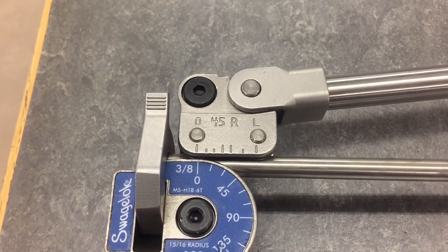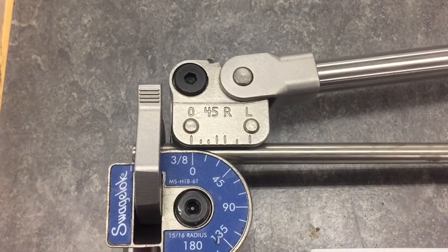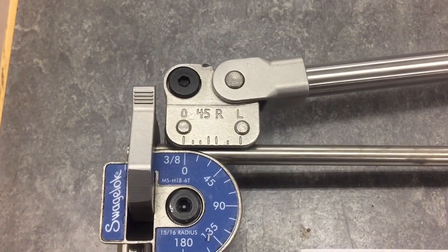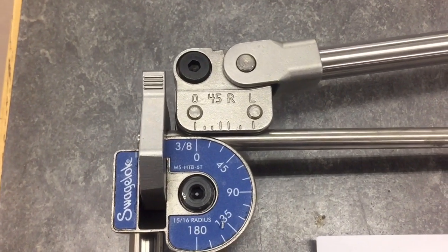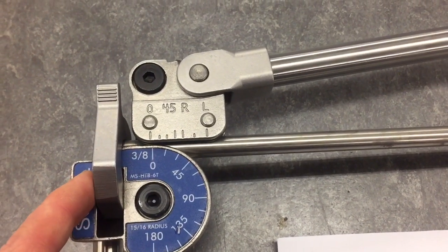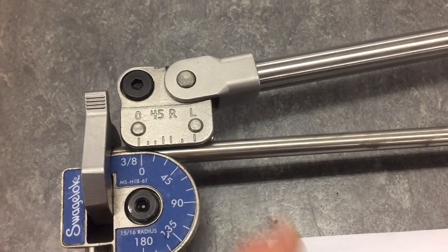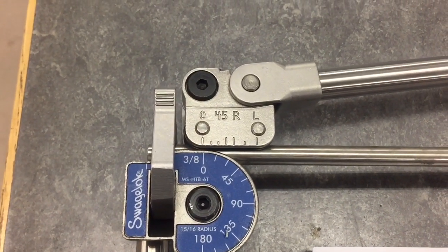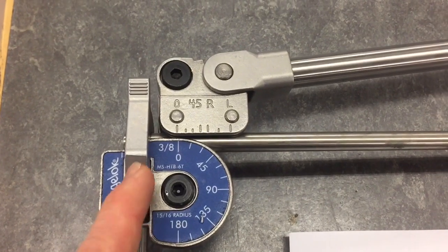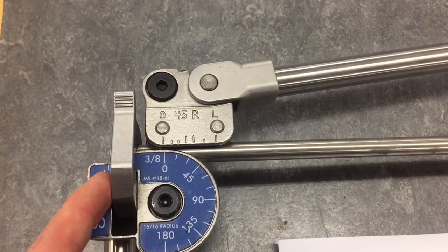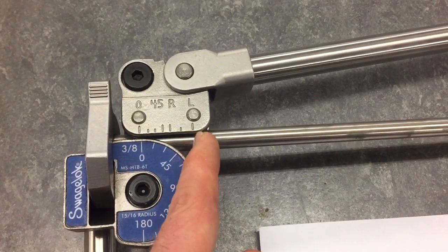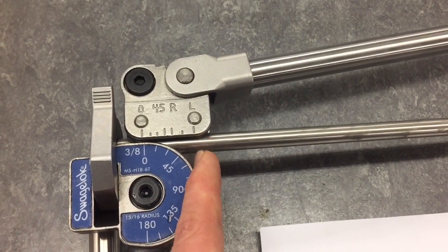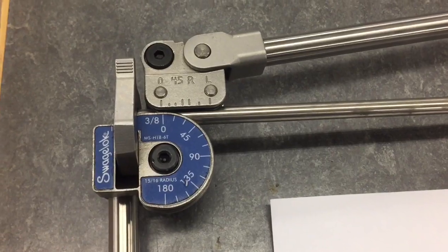So that comes into play when we're making a lot of our measurements, and we're going to demonstrate that here right away. What I want to do is measure from this reference mark out to L and see how far that is. Then we'll make our bend and make that same measurement again after we've bent it, and prove that the center of the tubing is now running parallel with that line for L there on the benders.